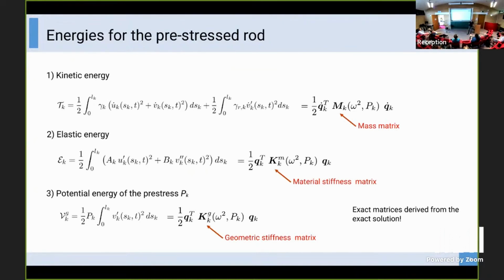Rayleigh beam model. This looks quite similar to Timoshenko, right? Yes, the Rayleigh beam model is a model in between Euler-Bernoulli and Timoshenko, because in addition to the Euler-Bernoulli beam, it has the rotational inertia term, but still assumes unshearability. In the Timoshenko beam, you also account for shear deformations. So it's more enhanced.